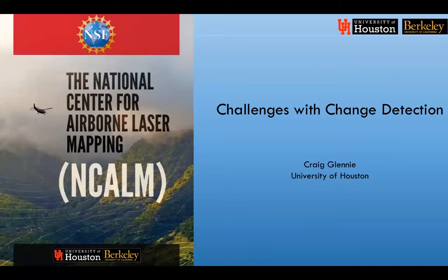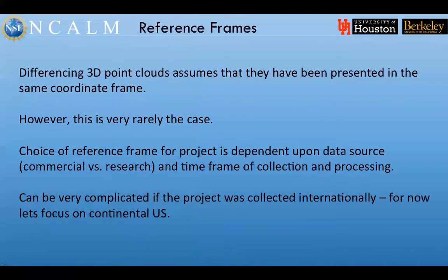And there are some challenges with some of these data sets. One of the biggest problems that we come across is the fact that the data are in different reference frames. Implicitly, when we're doing change detection, we're assuming that they're realized in the same coordinate frame. And if we do a difference between them, anything we see in the difference should be the change that we're looking at. The reality is almost every two LiDAR data sets are probably referenced to a slightly different reference